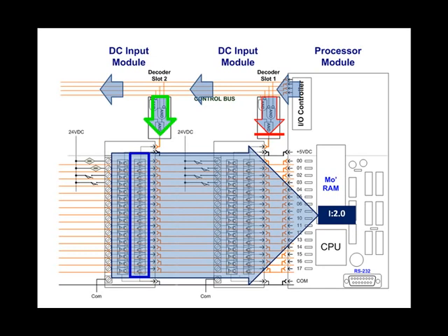Why not just hook all of the 16-bit cards, inputs and outputs, into a single data bus of 16 conductors going into one set of 16 screw terminals on the processor? Keep in mind, if we add some electronics to the processor, we can read inputs into memory, and when it comes time to do the outputs, we can read those out of memory out to the cards. You'll see this in a bit. So we're going to plug all of the input and output circuit cards into the same backplane, common bus, and let the processor sort this all out.